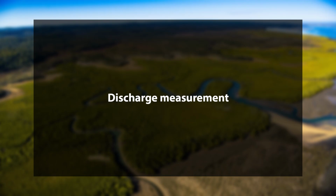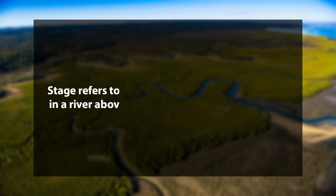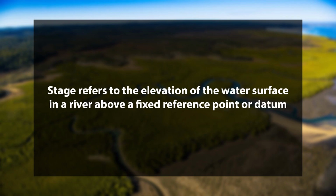Now, let us discuss discharge measurements. The continuous and accurate measurement of river discharge is a foundation of hydrological studies. It is measured using two common methods. First is the stage data. Stage refers to the elevation of the water surface in a river above a fixed reference point or datum. The datum is usually the river bed surface. Stage data is the most easily and continuously monitored hydraulic parameter.